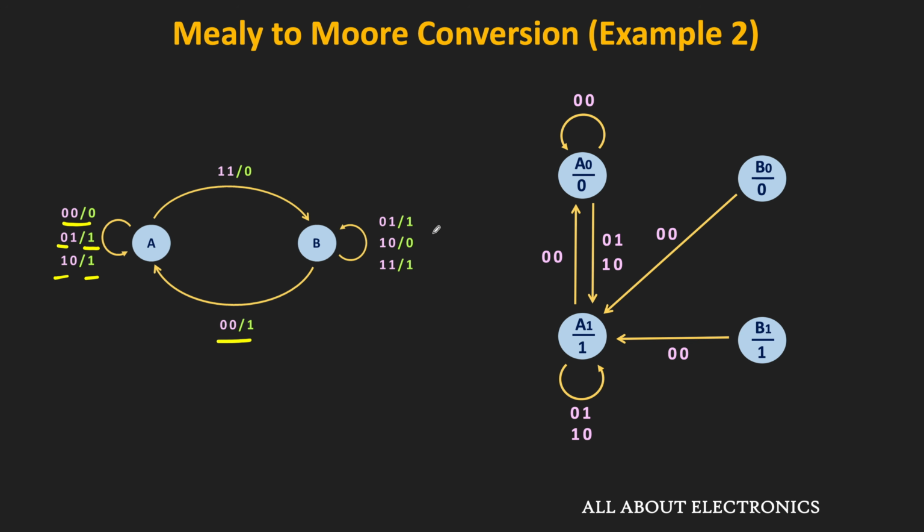So out of the three transitions, when the input is 1, 0, at that time, the output is equal to 0. So from the B0 state, for this 1, 0 input, it will remain in the same state. But if we see the B1 state, then it will go to the B0 state. Because in this B0 state only, the output of the machine is equal to 0.